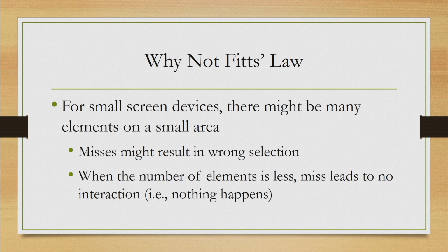It may also happen that in the small area we are not having many elements, and so we touched at a point which is not required, but nothing happens. So, effectively we wasted the effort and time required to perform that touch operation. So, in one case due to our error some other objects got selected, in other case nothing happens and we wasted the time and effort.